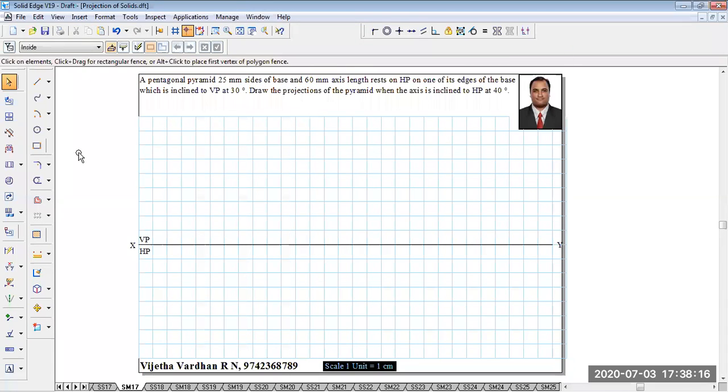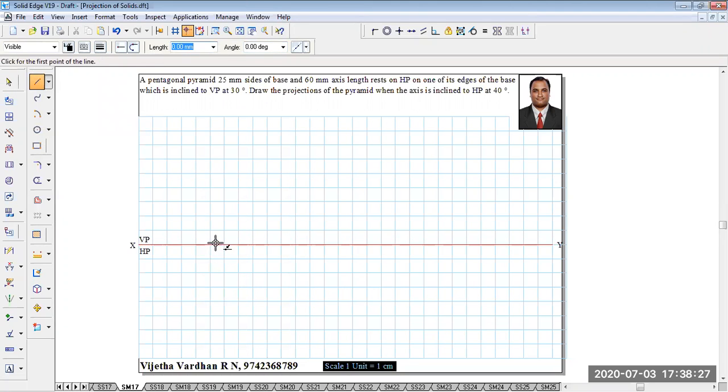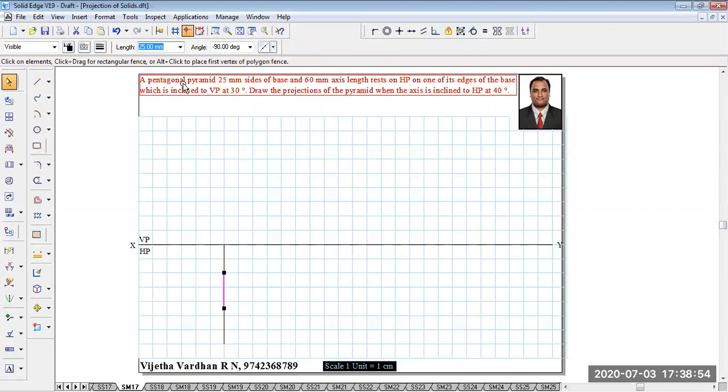Okay guys, this is what the grid book is going to look like. This is what the grid sheets constructed in my system. Now using your 2H pencils, keeping some convenient distance, for example over here, I'm going to draw a constructional line which is perpendicular to the XY line. After which, I'm going to take an HB pencil, and approximately from this position, that is after measuring 2 boxes, I'm going to measure 2.5 boxes as a dark line, which is going to represent one of the edges of the pentagon.